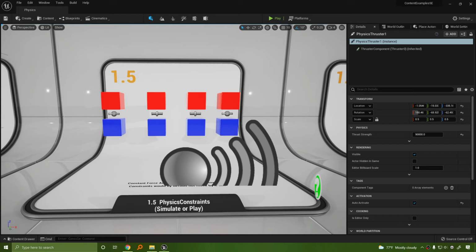Now, Unreal Engine 5 is really flexible in terms of what the constraint system is supposed to do, which allows designers to make many different types of joints simply by changing some options. This is all the same element, but with different options in the joint. The engine has a few default joints, like a ball and socket, a hinge, a prismatic, but they only differ in their settings. So you should be able to freely start playing around with any joint type and experiment with making your own configurations. In this particular content example, let's look at what's happening from left to right.